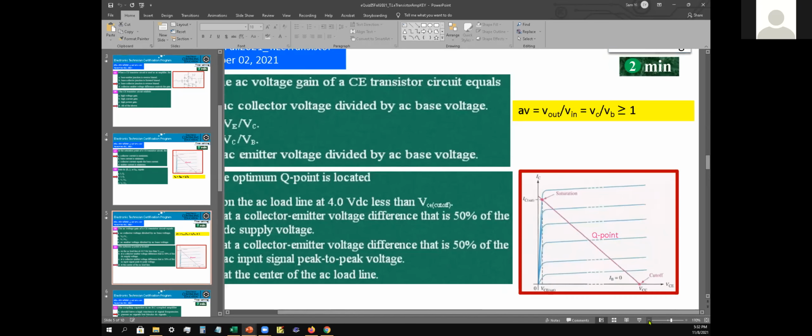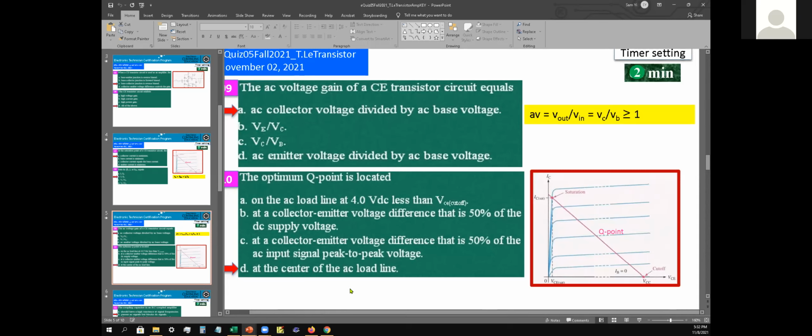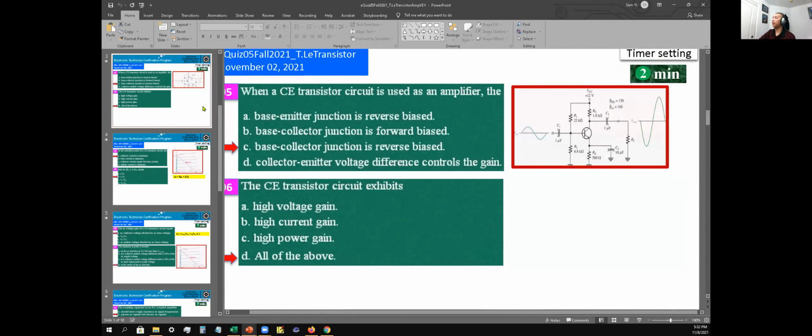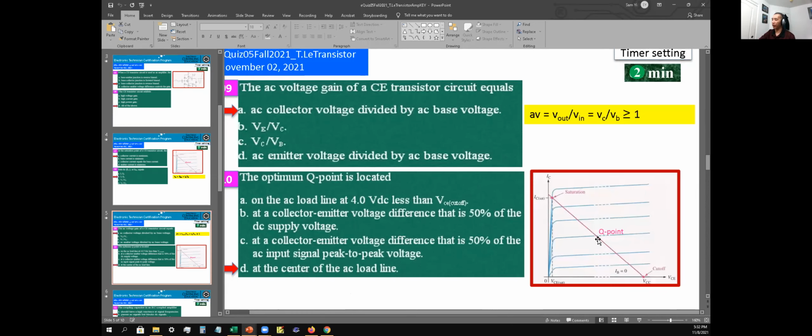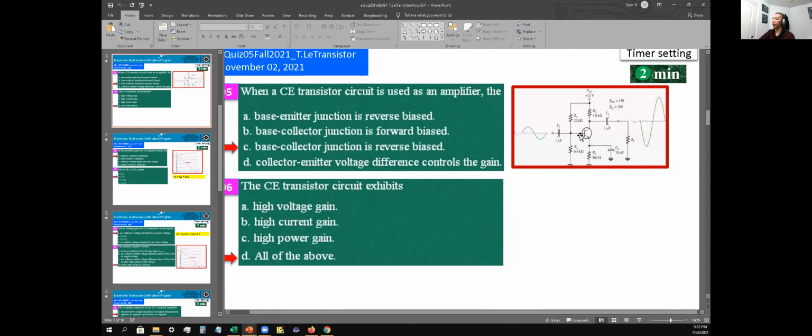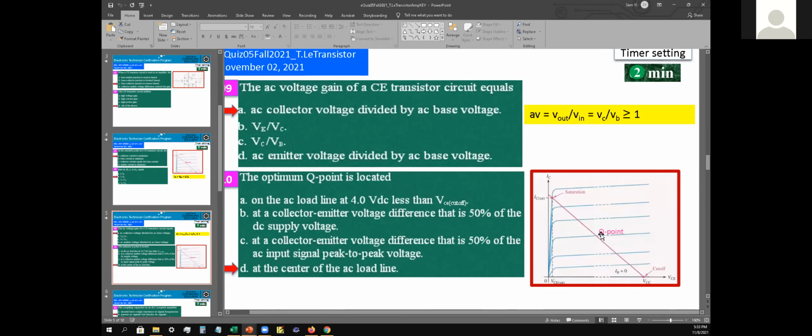Sorry, Sam, one more thing, just to understand: is the AC load line the same thing as the DC load line? Just so I'm clear, because you said DC load line was the answer, and clearly D does not say that. I thought they were different. Yeah, they're different. As we said a minute ago, the DC just biases the transistor, but the AC load line is the one we have to look at because that's where the current would be flowing. Okay, is the Q point then the center of both the DC and AC load lines regardless? Yes. Okay, thank you. You're welcome.